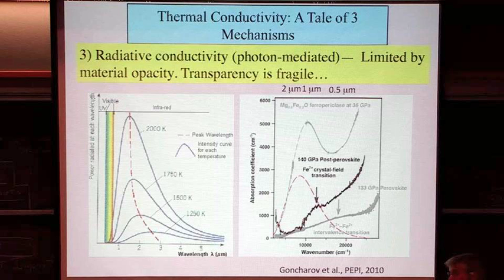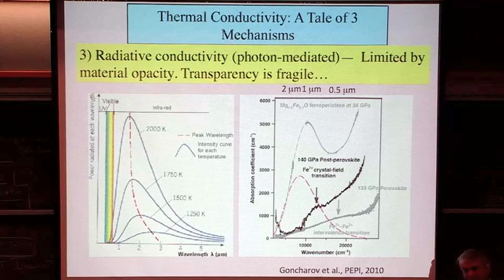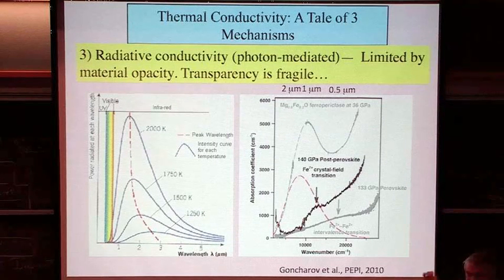So it is rather, well, let's put it this way. You would have to make a firm statement, you would have to know what the defect concentration is very accurately and know what the integrated spectrum looks like very accurately. And I've only talked about thus far the effects of nice things that just substitute into lattices, like iron, nickel, manganese, magnesium, for example. I haven't included grain boundaries at all in this.